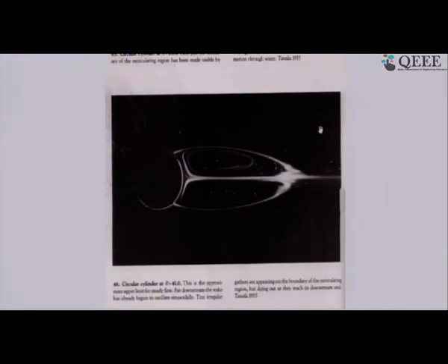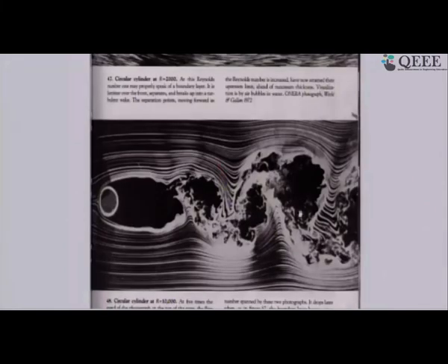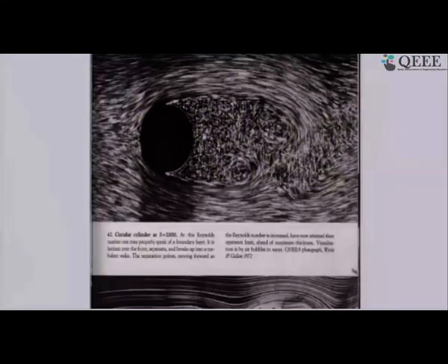What you saw here is that there is separation taking place over here, and this is the wake which is being formed. What has happened here is that the wake remains attached in this case, whereas at the larger Reynolds number, which is what we are looking at here, the inertia of the fluid is so much that it does not allow the wake to remain attached, and it alternately comes down and then moves like this, and then moves off there like that. So the wake is now not attached. The result is that at the back, you have a lot of fluid which is partially getting swept away at some point, and then it remains stagnant for some time, then again from here. So the wake causes alternatingly higher and lower heat transfer coefficients with time as the vortex keeps shedding. So this is what the separating wake does.